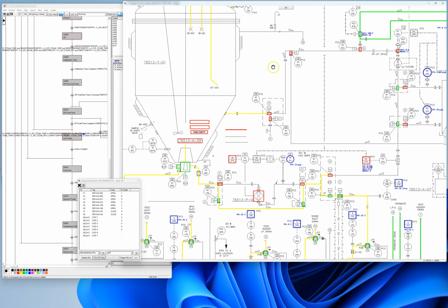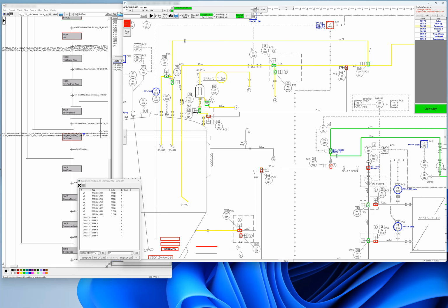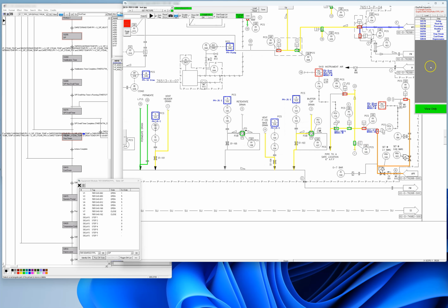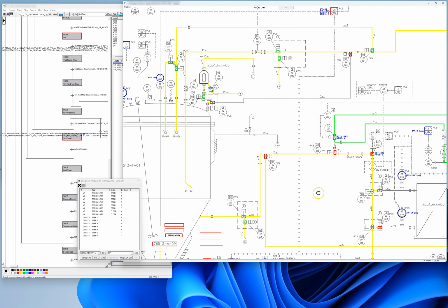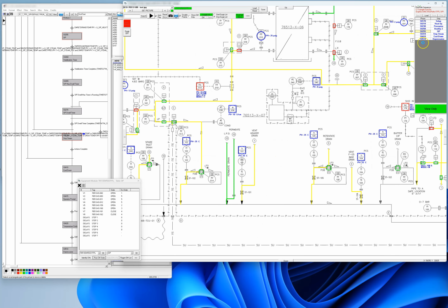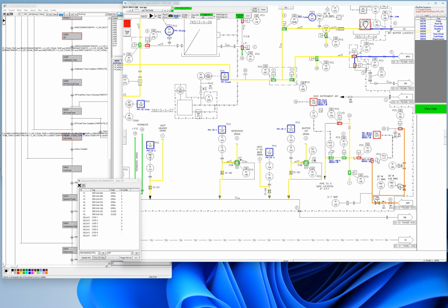This is actually the first stage of the heat up, and then it tries to not pressurize, but it does the steaming part. This is the second flow path, right, in here, and then heat up 2. Basically, that's pressurize and heat up is the same. And then you'll stabilize. It carries out SIP. Make sure all the temperatures are up to a certain dwell time and for a certain duration.